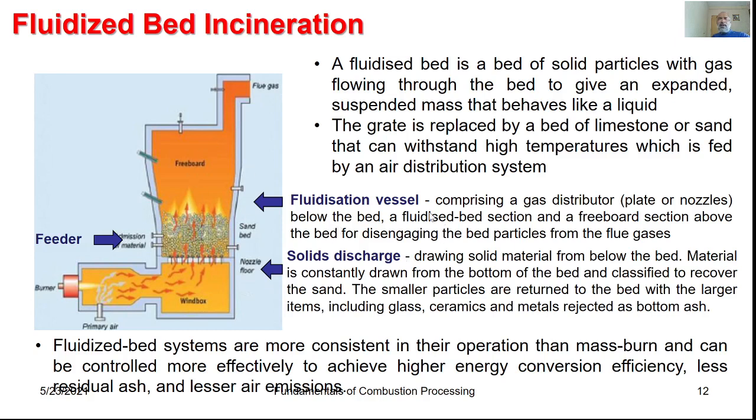This fluidized vessel comprises a gas distributor below the bed, a fluidized bed section, and a freeboard section above the bed for disengaging the bed particles from the fluid gas. Also, the solid discharge is drawing the solid materials from below the bed.